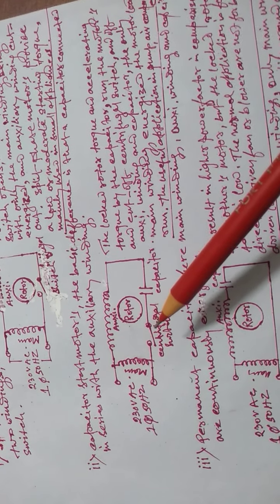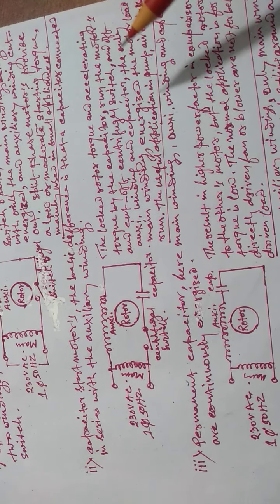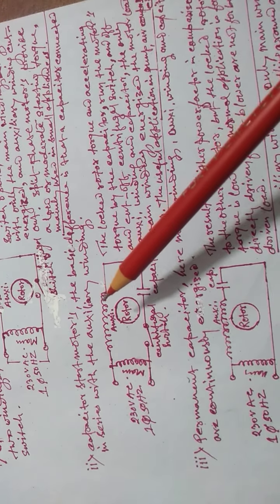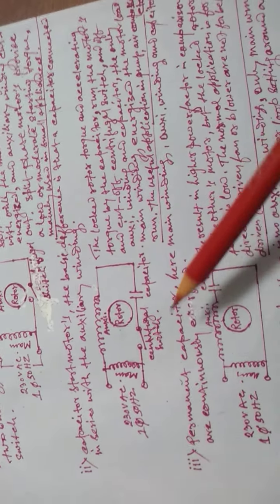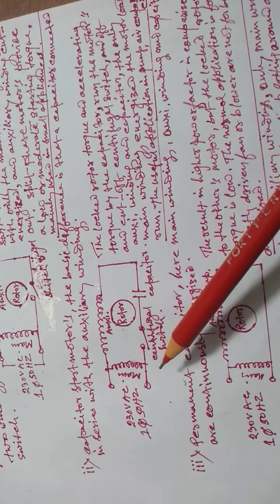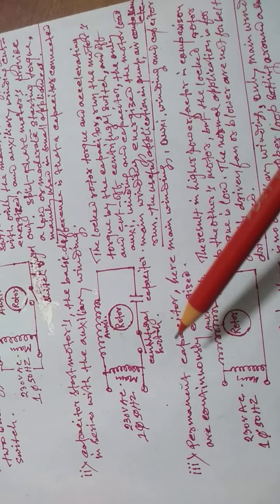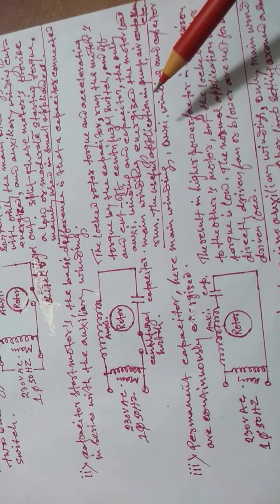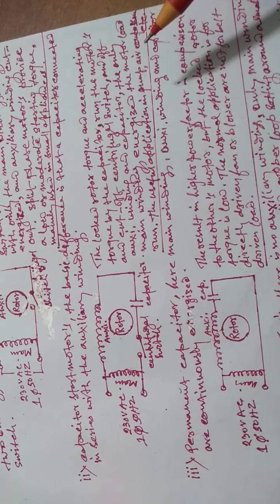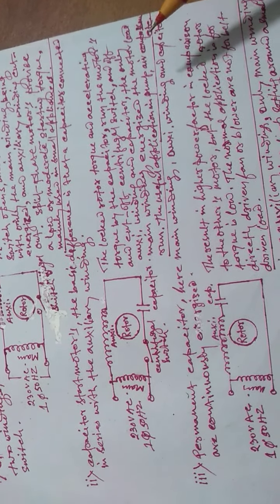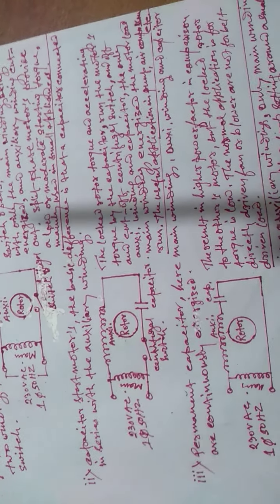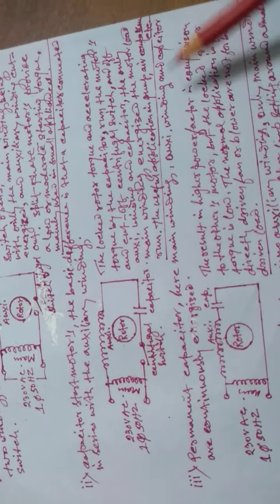This is the centrifugal switch off, with the capacitor and auxiliary winding off. The main winding is energized. The motor runs under load. Useful applications are pumps, air compressors, etc.